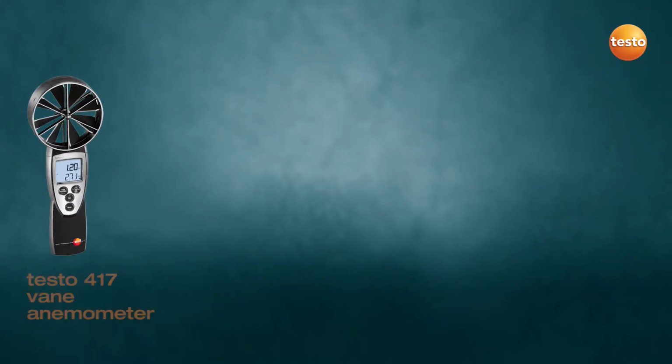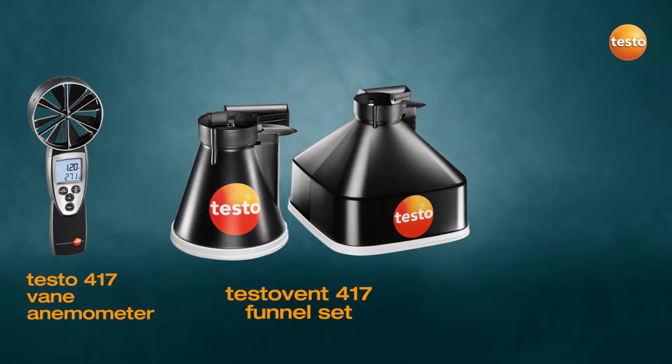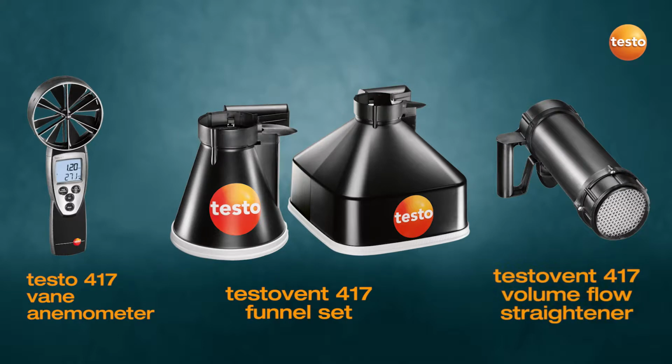You will be perfectly equipped for taking measurements at supply air and exhaust air outlets of a room ventilation system with the Testo 417 vane anemometer. It can be combined with two funnels, allowing volume flow measurement at grills and diffusers, and thanks to the testovent 417 volume flow straightener, it is also suitable for swirl outlets.